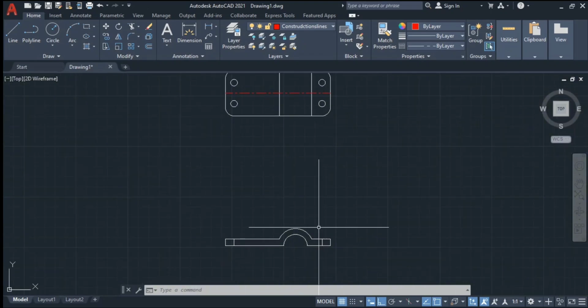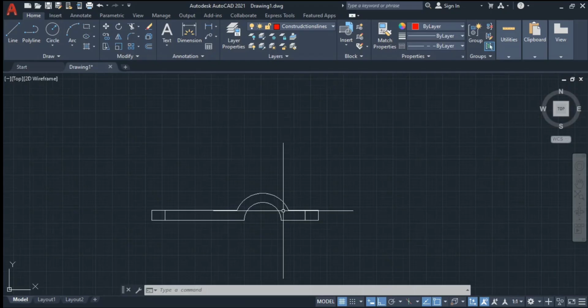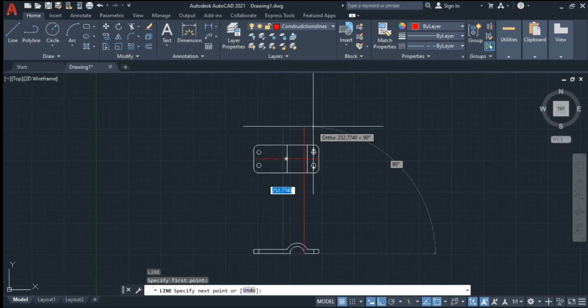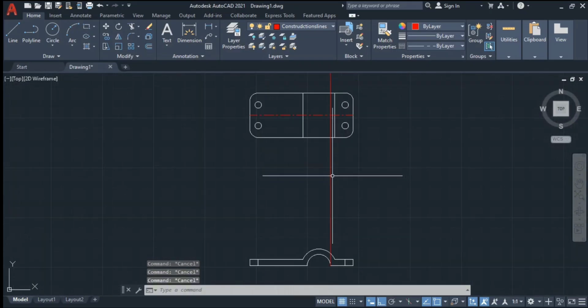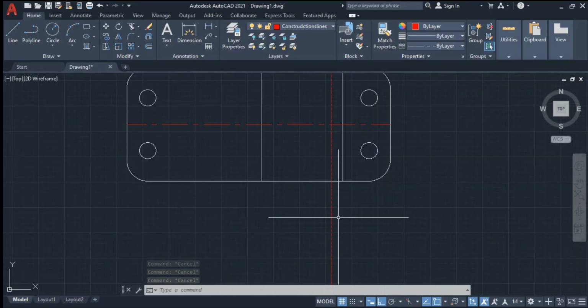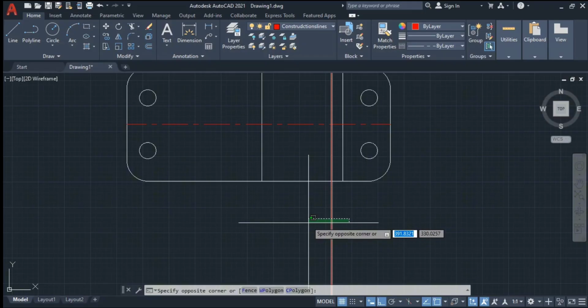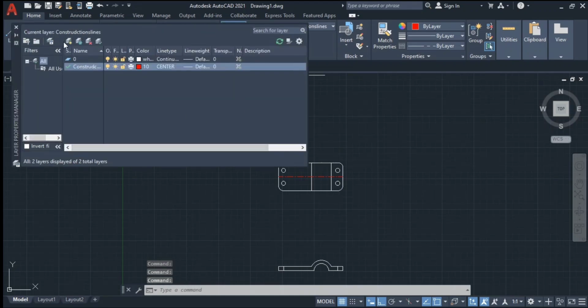See, so one more thing. Since it is a side view, you can see L, enter. There are a few lines which do not appear from the top view, but they can be seen from the bottom view. In order to show them, what we can call hidden lines, I am creating one more layer.